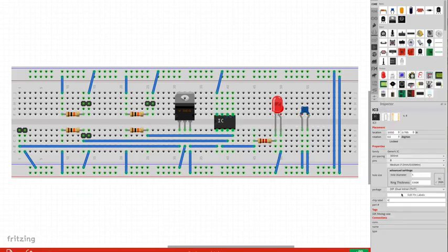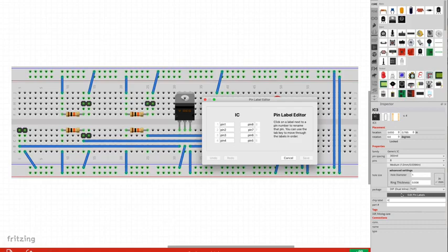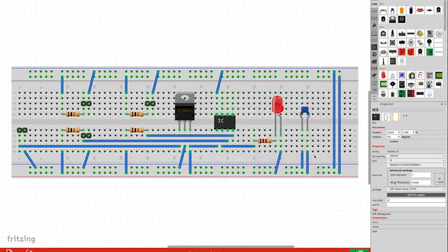You can also edit the pin labels. This is very important. So here we could decide that pin 1 is plus 5 volts, and that's 0 volts, which it typically is on a PIC. And the other thing we can do is change its chip label. We want this to be a PIC, but we know exactly what PIC it is, so we might as well give it the correct number. And there you are. So now we know exactly what we're using in the final design.